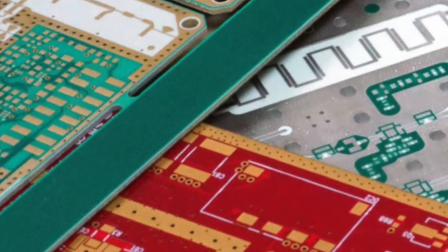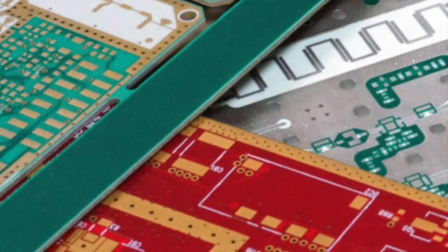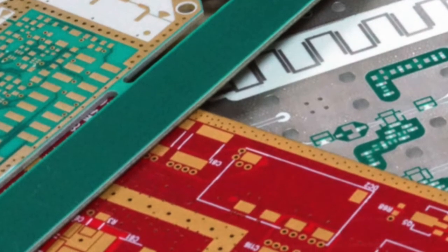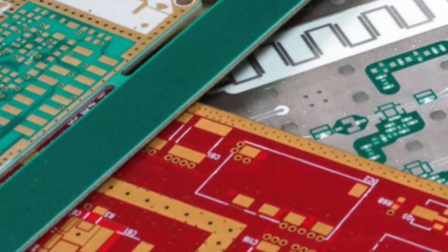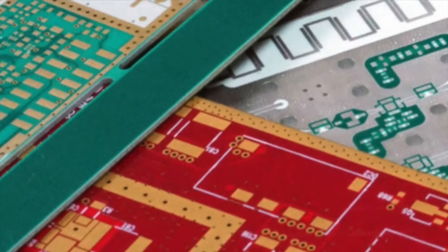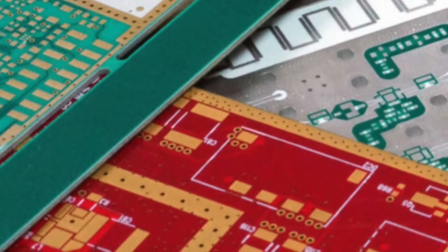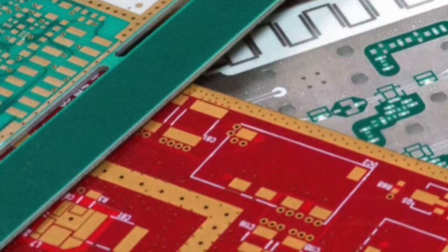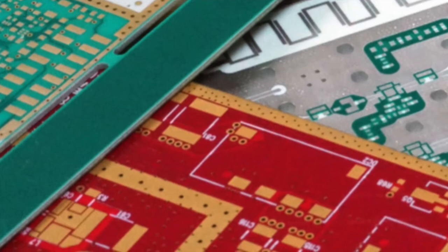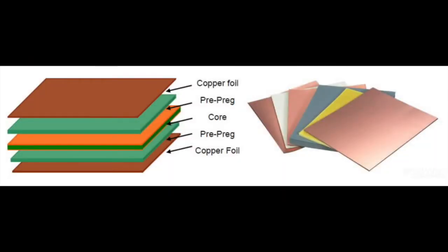And then we range to the ultra low loss, and these are materials that are designed to be utilized up into the upper gigahertz. And by that, I mean generally the millimeter wave and above. This is where you're approaching 30, 40 gigahertz up to one of the most widely used applications, which is vehicular collision avoidance, which would be 77 gigahertz.